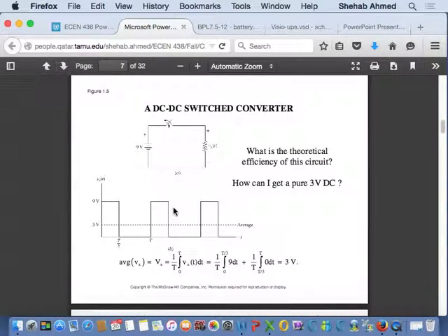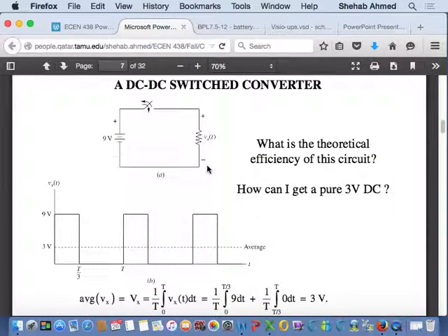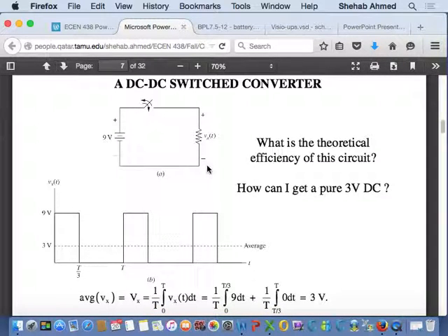And we talked about our alternative. Our alternative in power electronics, okay, remove this resistor and don't put a classical linear type MOSFET circuit, and operate the MOSFET in saturation and cutoff regions and make it look like an ideal switch, right?